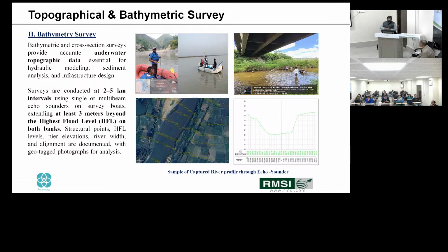So wherever water is there, there's a technology called echo sounder. Like how we are using a laser there, here we are using a sound wave, sonar. So sending a sound pulse, we get the return. From that you can measure the accurate depth of the water. The river bed is also important, because now we have above ground and river bed put together giving the complete picture of the terrain. So that's what we have already completed.